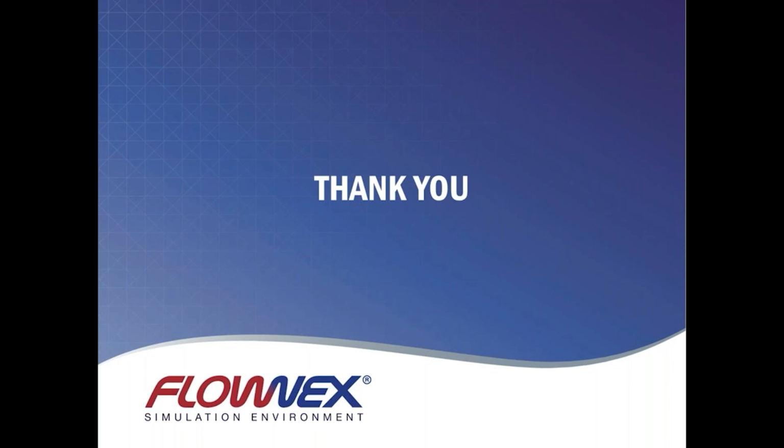There are many other possibilities as well with the Flownex applications. This can be, as I mentioned, testing new control philosophies. You could even go as far as pre-tuning controllers before commissioning. So perhaps you're designing a new plant. You can build the entire control system in Flownex, pre-tune the controllers, and when it comes to commissioning, you give the control engineer a very good estimate of what the tuning values should be. They can implement those and test that the plant works from that point. So it saves a lot of time in doing step tests on your plant or trying to test control philosophies and modify them during the commissioning stage. You can do this instead in the conceptual design stage and shorten your entire commissioning times.